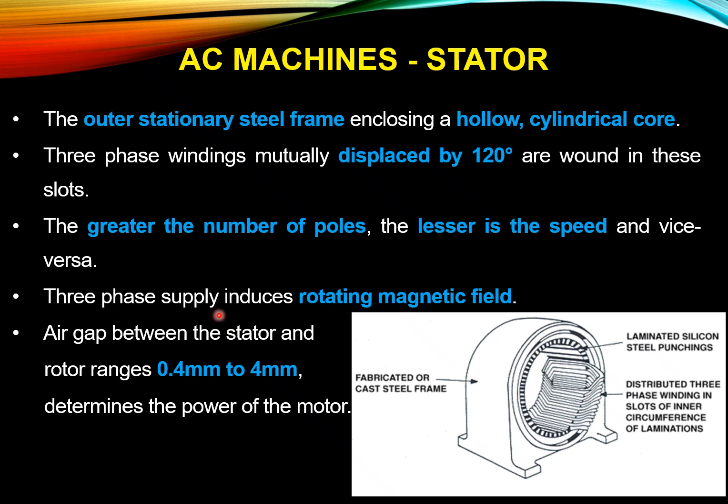The three-phase supply induces a rotating magnetic field. When it energizes, it will create a rotating magnetic field inside. When the rotor is inside, the distance between the stator and rotor creates an air gap. Usually it is 0.5 millimeters, very small, but it makes a lot of difference, and goes up to 4 millimeters. Usually the closer it is, the more the power of the motor.